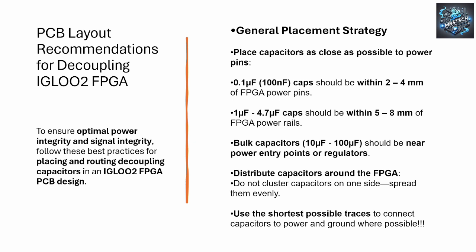Okay, there are plots showing that you can push all your decoupling capacitors up one edge of the board and still meet a low PDN, right? And the graph might show that. But in truth, what happens is, depending on the system and depending on the current demand at that time, you are pulling current across the board. It's not always a certainty that your interplane board capacitance will suffice.